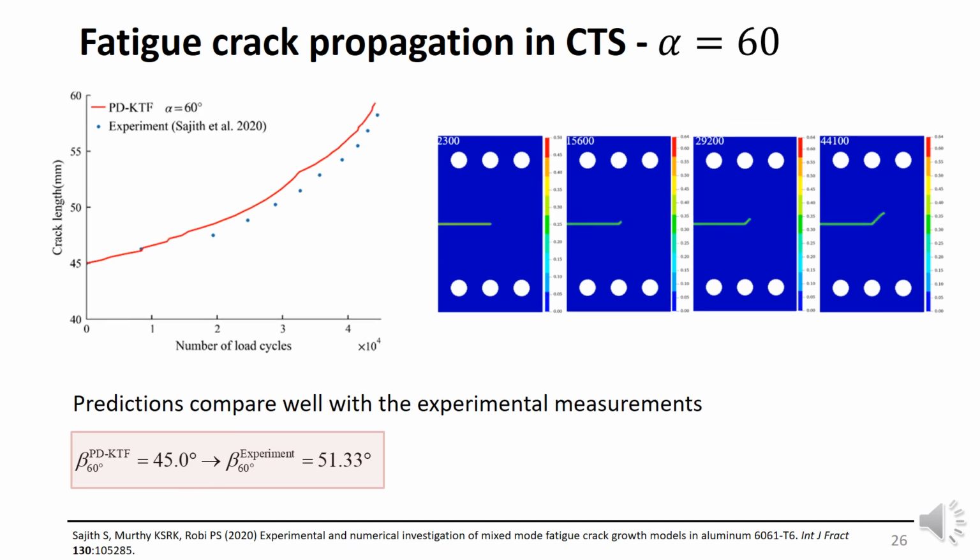If I go to 60, again, predictions compare well with the experimental measurements. We have 45 degrees versus 51. The crack length versus number of load cycles very nicely agree.